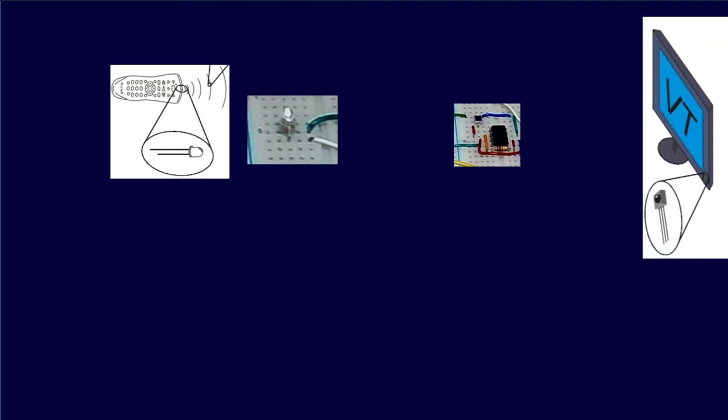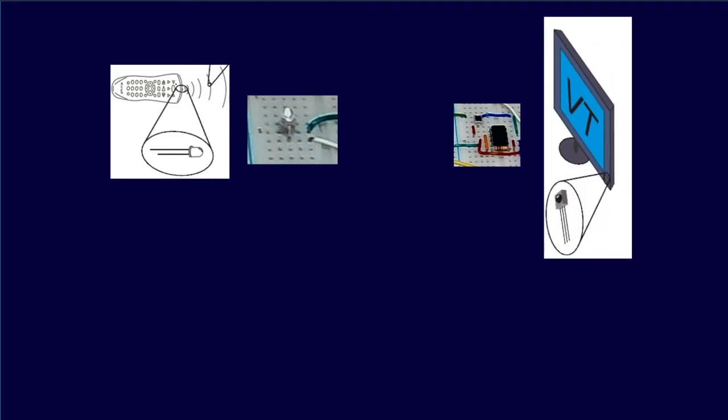In the following, another similar demonstration of Lab 6 circuits is presented. It is different from the other demonstration. Here it simulates the case of the remote control. An LED will act as the remote control, but with 9 kHz modulation, which matches the band-pass filter in Lab 6. The photoreceiver that was built in Lab 4 will assume the role of the IR receiver on the appliance.